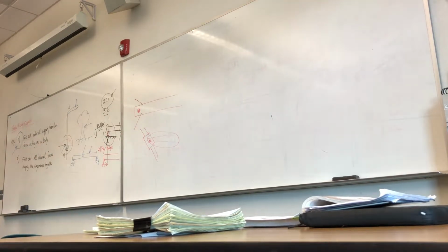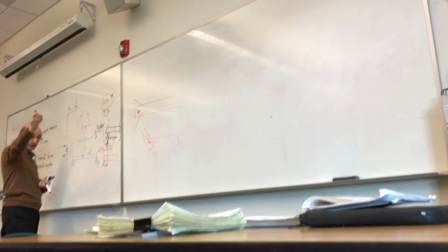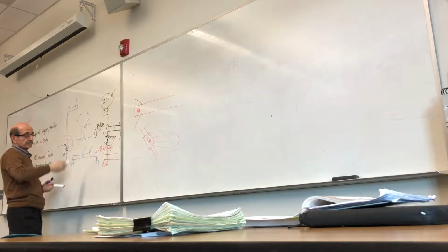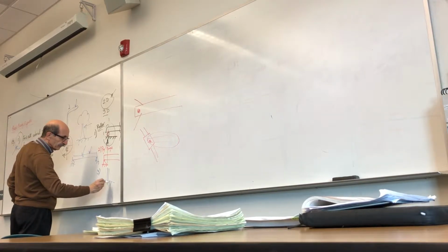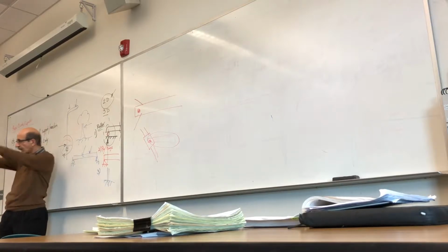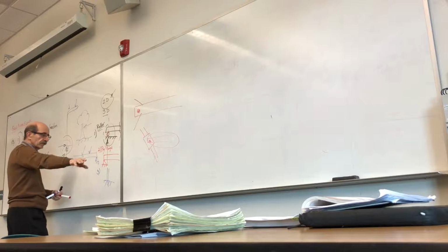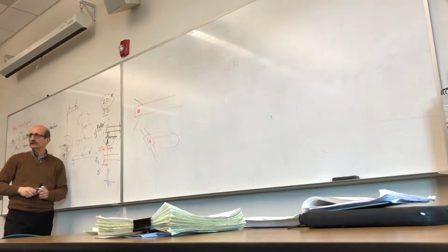Okay. Then there is another type of support, the root of a tree, or this light pole in the ground that is fixed, the foundation of a building, poured concrete, this is in place. Motion in this direction is not allowed, motion in this direction is not allowed, and rotation is not allowed.